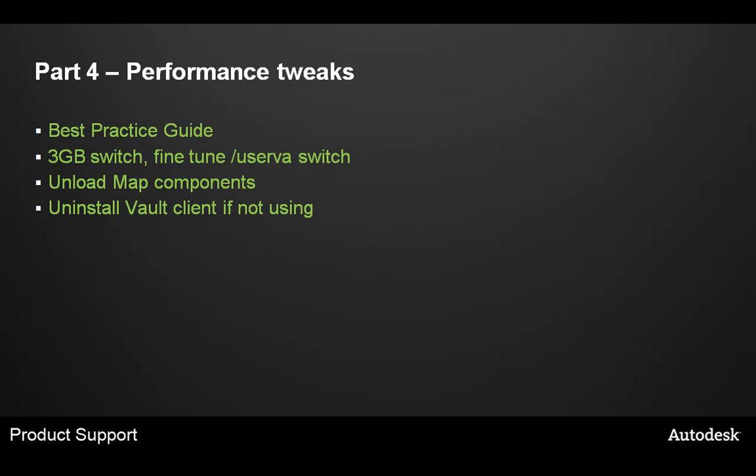Now, in that solution, it also describes if you use map just once in a while, you can still turn it off by default, and then during a drawing session you can still type in a command and enable map to run, but then the next time you start Civil, it'll still be disabled. Okay, but we give you the option of the 2 desktop shortcuts, one that will turn that functionality off and one that turns it back on.